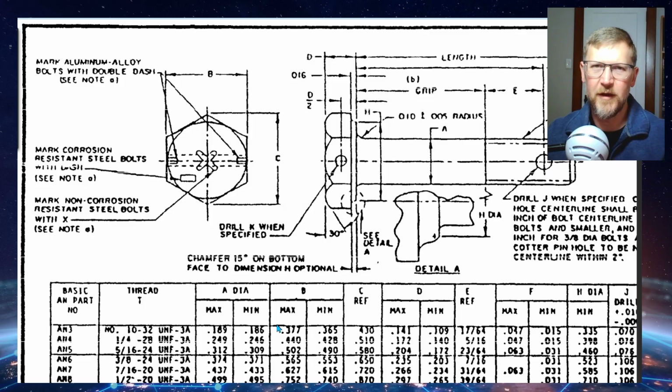So you need to make sure that when you're sizing a hole for this bolt to go into, you've accounted for the potential variation in the bolt diameter. And if you want the bolt to go in freely, you don't want the hole to be smaller than this 189, or even at that 189, because now the friction and the interference is going to be too much.